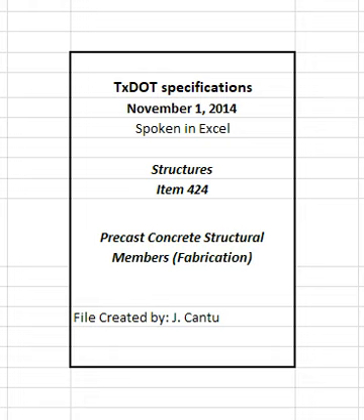Single-strand stressing jacks for pre-tensioning must have provisions for measuring the elongation directly on the strand. Multi-strand detensioning jacks must have sufficient capacity and throw to permit simultaneous release of the entire load in the strands. Use an approved single-strand flame release procedure to release the remaining load if there is not enough throw in the multi-strand jacks to release all load in the strands.